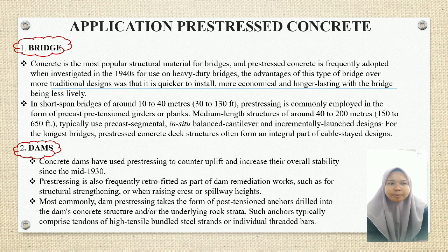Okay, next, applications of prestressed concrete. Prestressed concrete can be applied to bridges. Concrete is the most popular structural material for bridges, and prestressed concrete is frequently adopted, having been investigated in the 1940s for use on heavy-duty bridges. The advantage of this type of bridge over more traditional designs was that it is quicker to install, more economical, and longer lasting, with the bridge being less lively.